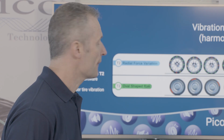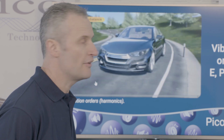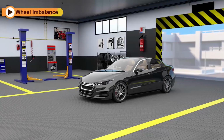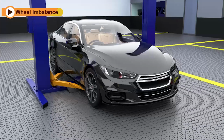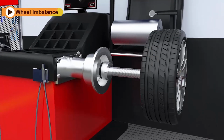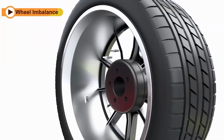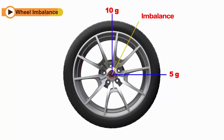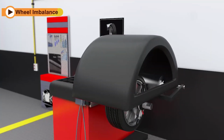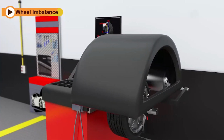Yes. So the animation now will take us through vibration orders and hopefully bring this to life. Here we have wheel imbalance. The wheel is going to come off the vehicle in the workshop, and we're going to balance this wheel. Important to note here that because we put 2 weights on a wheel, we don't then have 2 disturbances per revolution. Here we've applied a 10 gram and a 5 gram weight. The imbalance is in the vector sum of those 2. So an imbalanced wheel will only give us a first order vibration, and that's an important piece to remember.